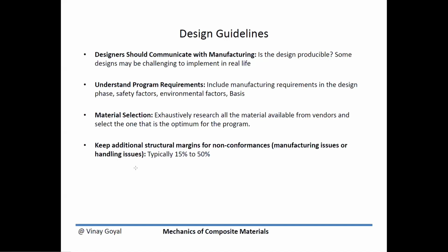Well, you can put your design forth, but then you have to make sure that you're flexible at modifying those designs to meet the program requirements. It's also important to make sure that the structure is manufacturable. So we also want to make sure the size, the weight, all that stuff is accounted for, and that the materials are compatible with whatever is going to be touching. We don't want galvanic corrosion, for example. So keeping all that in mind is very important.